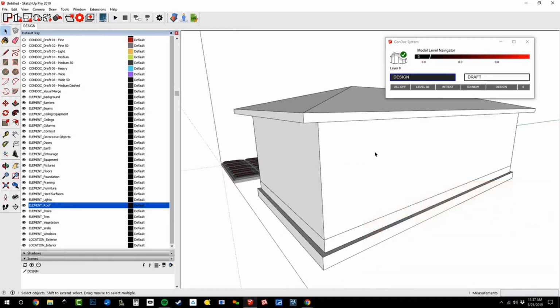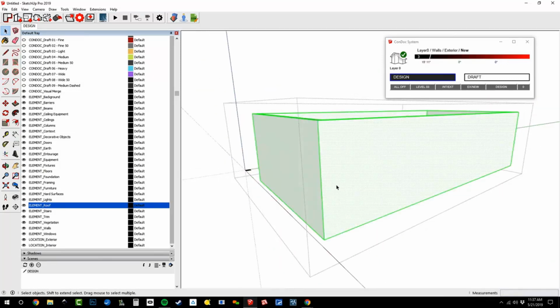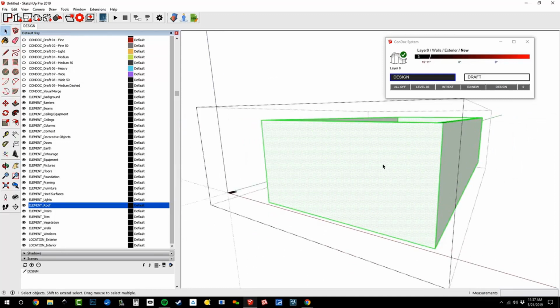All right. So once you're ready to continue to work on this thing, I just need to drill in here. And then I'll use my select tool, double click on this surface here. I'll hold Control and Shift, and then remove the surface and the edge from my selection, and then just do an offset like that. Then I'm going to use my select tool to pre-select this surface and use my scale tool. And if I scale it and click to finish, I can easily type in 7 feet, enter, and scale that piece to be exactly 7 feet.